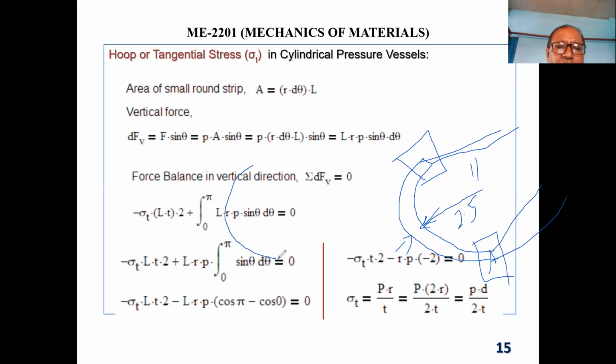You roll down to this way, okay? But material try to go back in initial shape. So we try to move along this direction and try to go flat. And over the time, its radius is increased. Okay. So what we did, we send it back to company again. They did the annealing, heat treatment, then roll it again. Okay. So what I'm saying, this is very expensive and also complex.